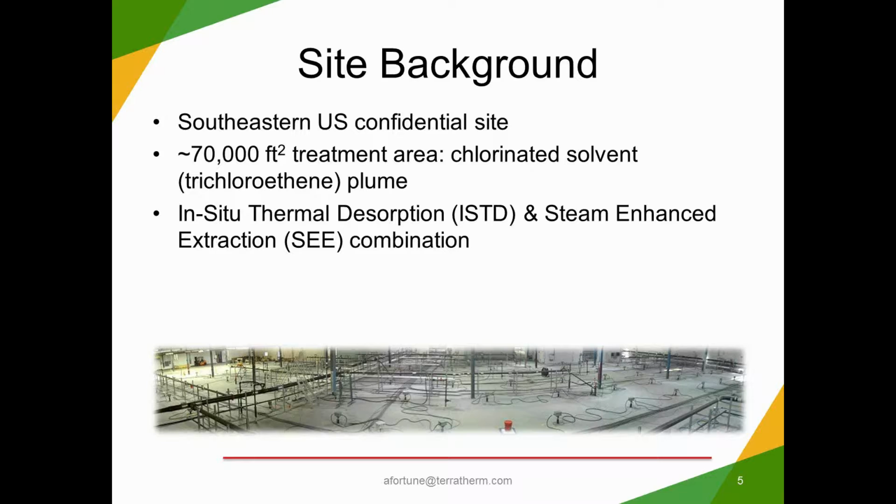TerraTherm was designing and constructing and operating this combination thermal remediation system, which was a supplemental remedy for the groundwater recovery and treatment system that was operated by others. We had performance criteria which was based on temperature, reaching certain temperature goals. And you can see a photograph of part of the treatment area.